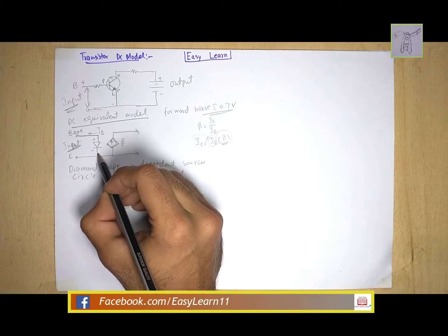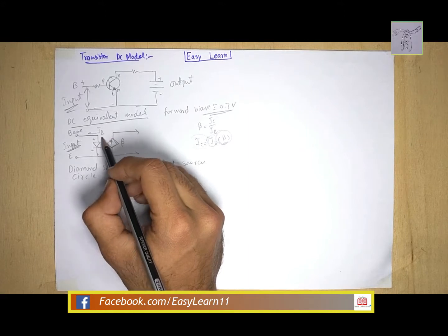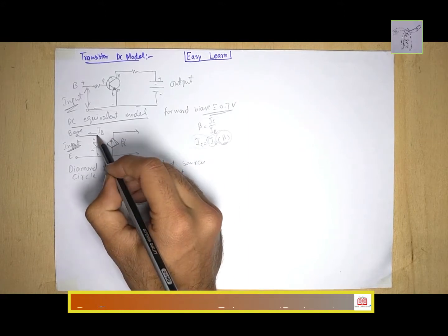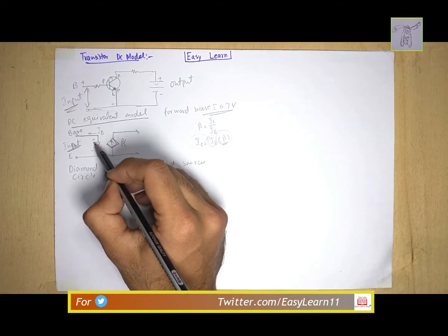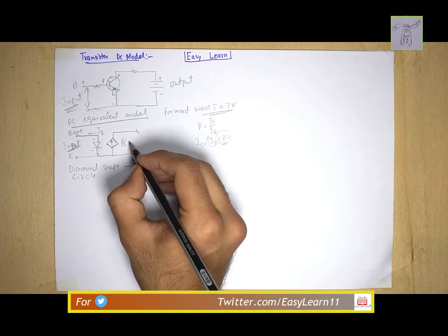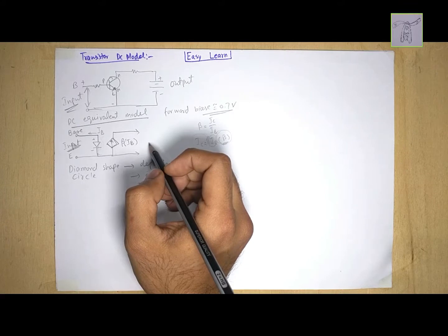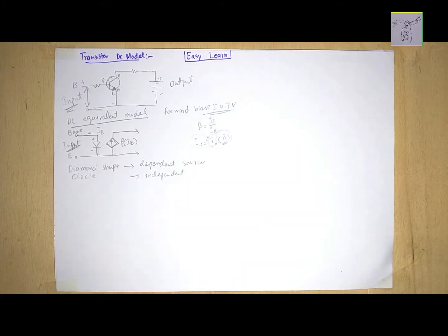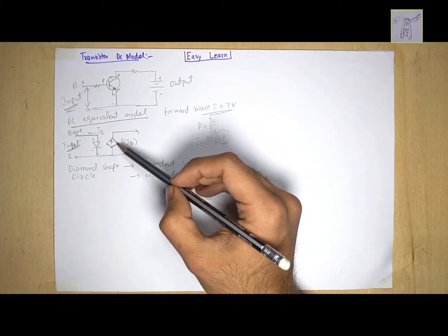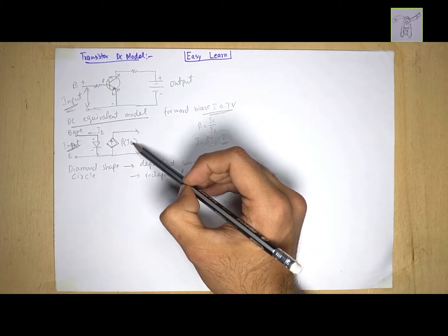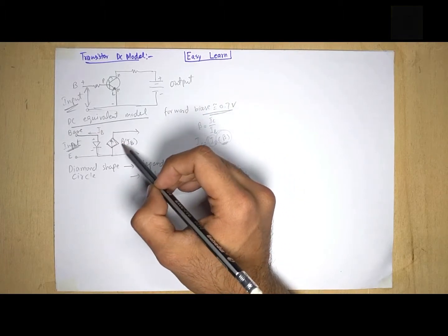If the base current is forward biasing this region, and with the quantity of current that is available, this current after passing through and after the drops will reach here. Then the base current IB multiplies with this boosting factor, that is beta DC. We already discussed beta DC in the previous episode. It is multiplied with this IB, so beta DC is a dependent source on IB, that's why we use this symbol.